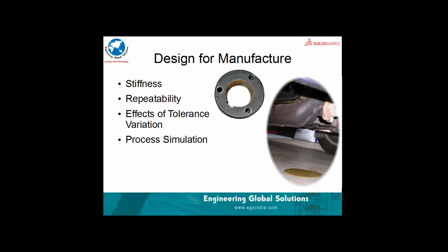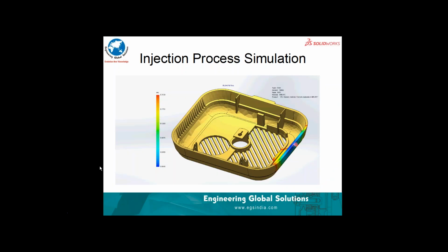But then the next question that comes up is, in design for manufacture, I need a certain flatness tolerance on the components which are mating together for this leakage problem to be avoided. Now if I give those flatness tolerances on the drawing, but I'm not able to achieve it in the manufacturing process, is it a design problem or is it a manufacturing problem? When you look at the stiffness which is coming up front in the first list of items in the DFM, that's where the culprit lies. We will be looking at it more down the line.